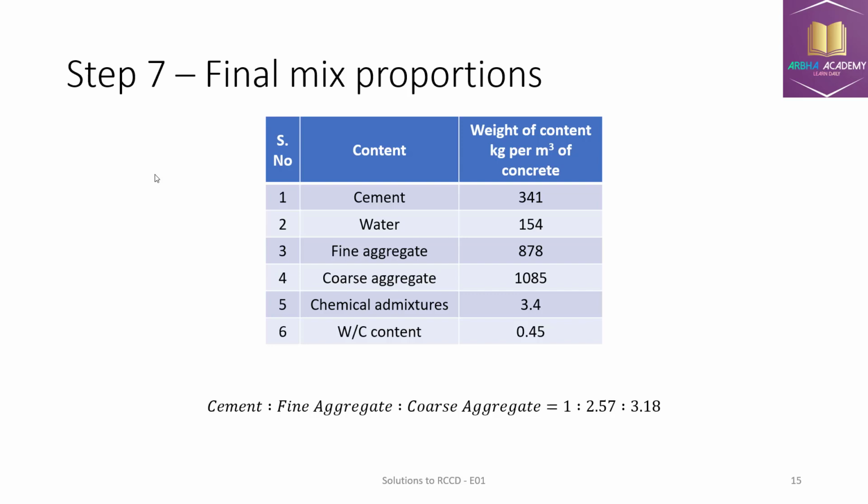This is not the final value of the mix design, because once this mix design is arrived at, we need to put up the cubes. They need to be cast. The cubes need to be cured. Then they need to be compression tested. And based on the compression test, the final adjustments in the mix design, if required, need to be made. And then only the final mix ratio can be confirmed. So this is how the mix design is created. I hope from this video you now know how to calculate the mix design as per Indian Standard 10262.